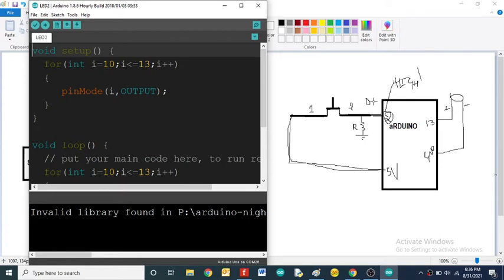Here we'll get two types of information. How are you going to get to know whether the switch is pressed or not? Based on this operation, when the pin provides 0 value, the switch is not pressed. When the pin gives a high level value, the switch is pressed. Only two conditions. So based on this requirement, you have to write the code here.